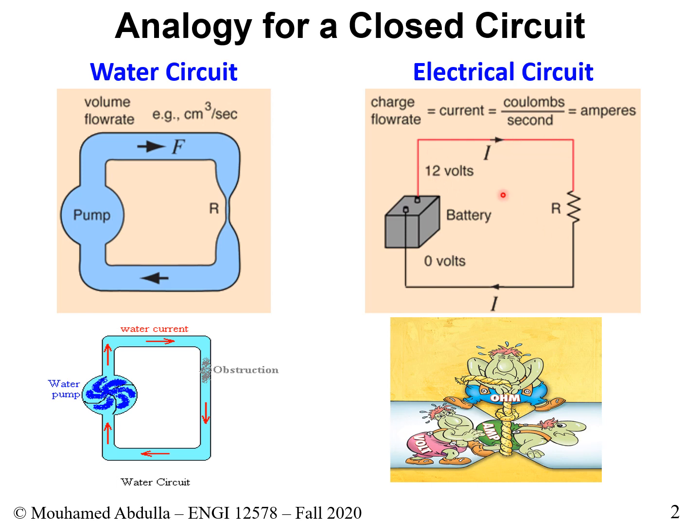One thing you should realize between current, voltage, and resistance is that current goes through the resistor. Voltage is across the resistor. That's why in the lab, if you were to measure the voltage across a resistor, you put your leads or your alligator clip on this side and on this side. You connect them, and that gives you the voltage across the resistor. If you want to measure the current through the resistor, you have to break the circuit, literally cut it, and you connect this.